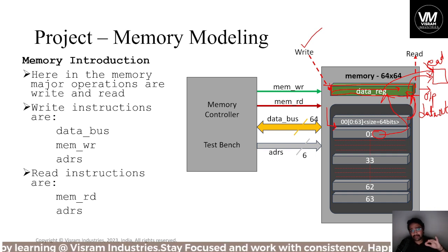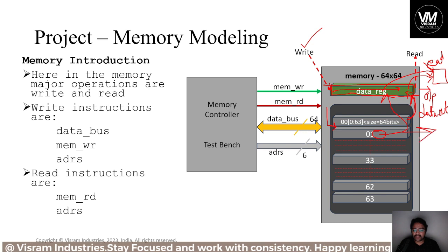But in some memory designs, the access of the data can be done in a single click, where it goes directly without any temporary variable. Those kinds of memories are different. So the basic structure I'm explaining is a bare minimum memory design, which you can understand from designing in Verilog HDL as well. This is a basic and most used kind of structure in memories.